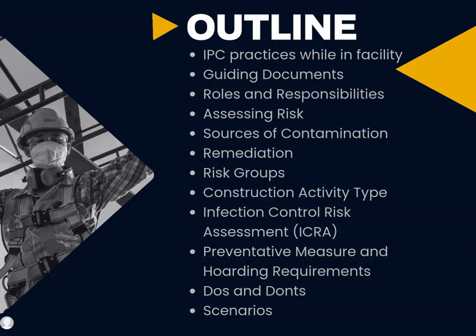Today's presentation will cover IPC practices required when working within healthcare facilities, guiding documents that support CRM projects, roles and responsibilities of key stakeholders involved in CRM, risk assessment, including sources of contamination and remediation practices. We will review the Infection Control Risk Assessment, also known as an ICRA, including how to determine population risk group, construction activity types, and how to use the ICRA matrix to identify required preventative measures.